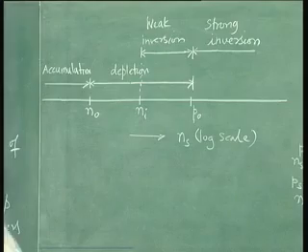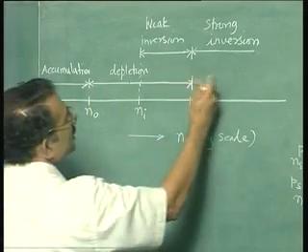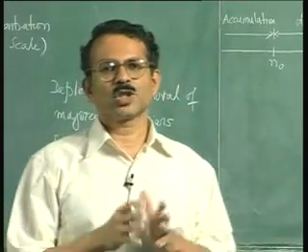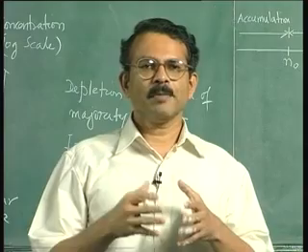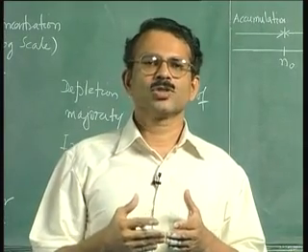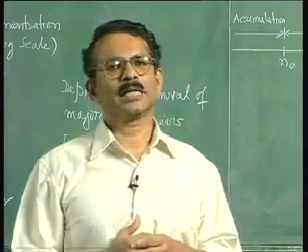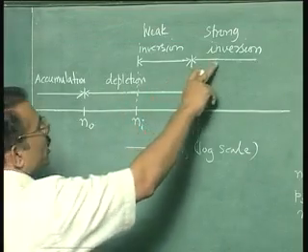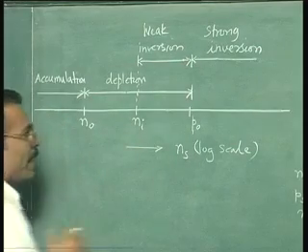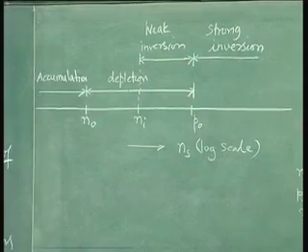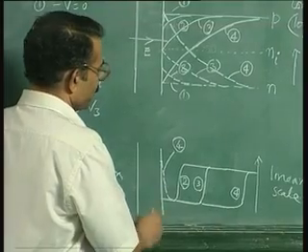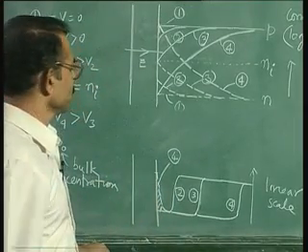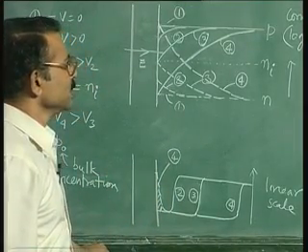Now in our first course what we said is that we will call this region the inversion region. Whenever we use the word inversion, it would imply strong inversion. The treatment of weak inversion is more complex, so that is taken up in advanced courses on semiconductor devices. Now what is it that distinguishes strong inversion from weak inversion? The pileup of the electron charge at the interface as shown in this diagram, that is this area, starts becoming significant in the strong inversion region.